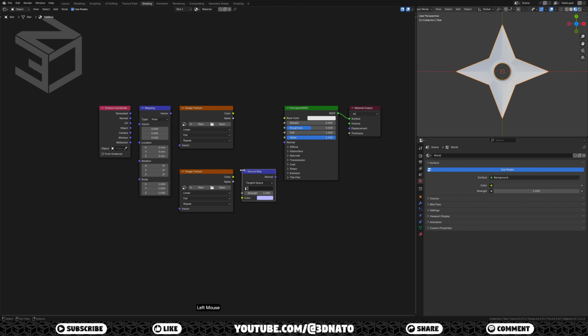Now let's start connecting these nodes to create the material. Connect the Texture Coordinate UV to the Mapping Vector socket. Connect the Mapping Vector to both Image Texture Vector sockets. Load the Roughness map and set it to non-color. Load the Normal GL map and set it to non-color.